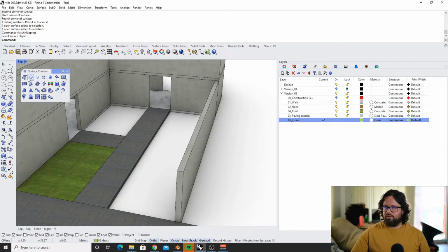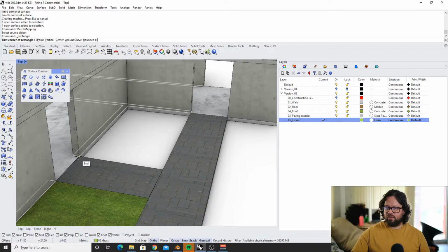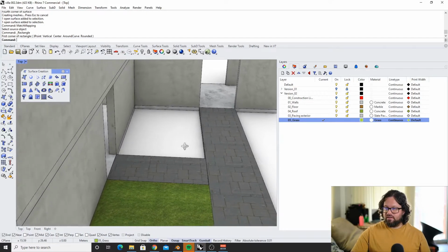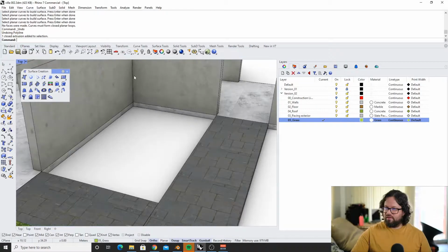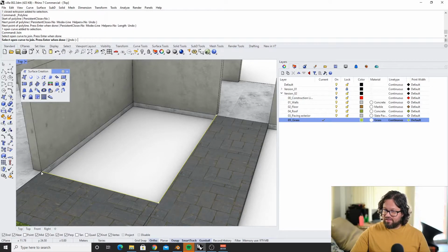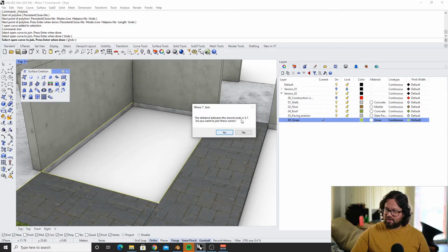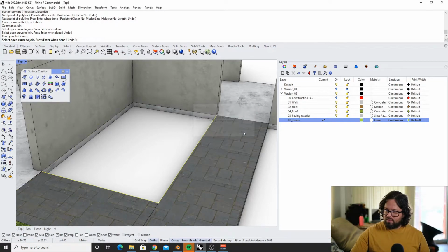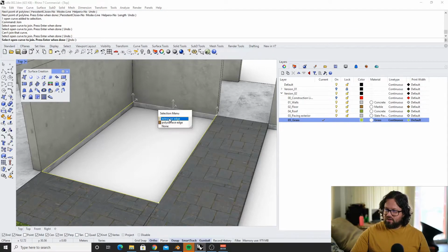I use this one. If I want to use this tool, then I need to actually have a line drawn here. Or I can actually use the edges of the surface. That's also possible. If you don't want to draw all the lines here, you could do this. You draw one line. I mean, this is very lazy, but you draw one line and join edges. If you do this, you actually extract the edge as a line, and here it says these don't work. So I need to, yeah, this one works. It actually extracts the edge of the surface to connect to the line.